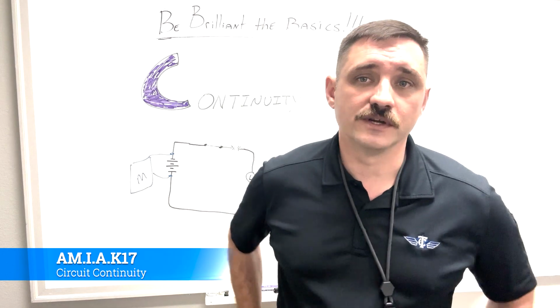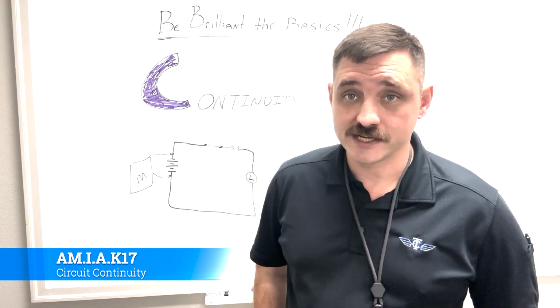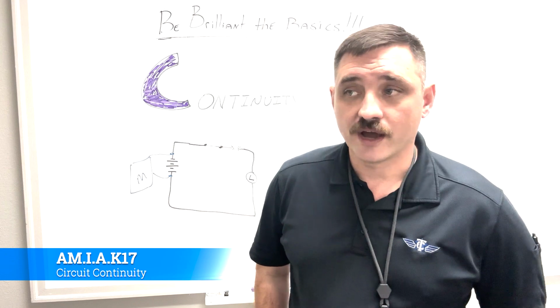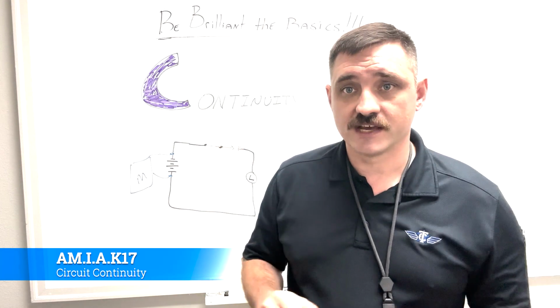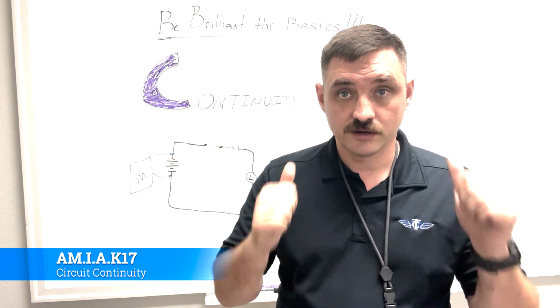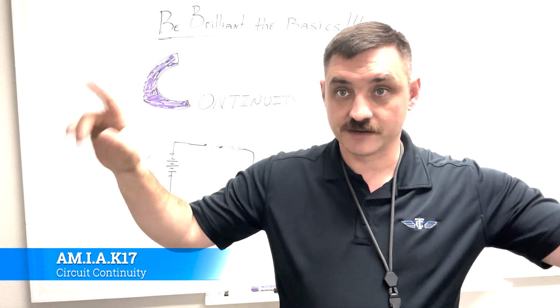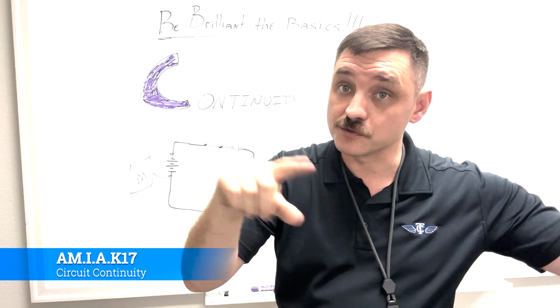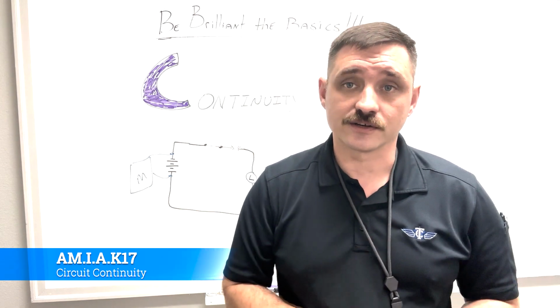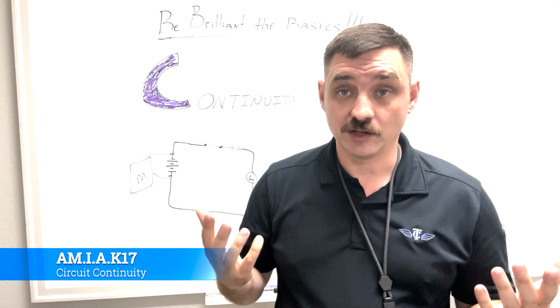One of the trickiest ones, however, and this is one that you will see, is corrosion. If you go back to your 737, looking at the aircraft forward, you have your big wall full of hydraulic stuff, and you'll have wire runs that go through there. Well, in those wire runs are connectors. Those connectors get exposed to all sorts of elements.